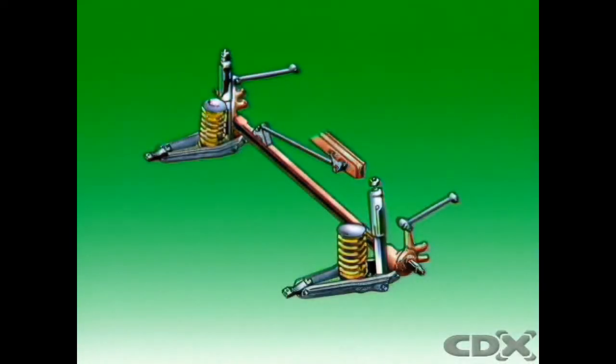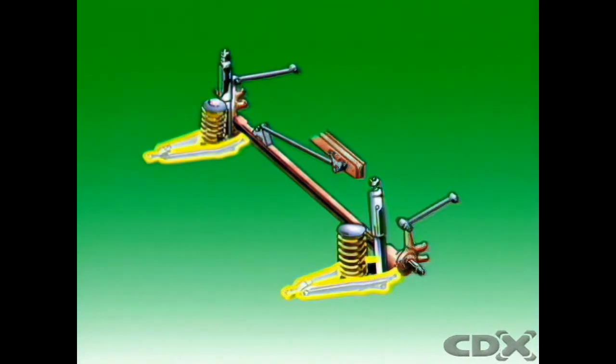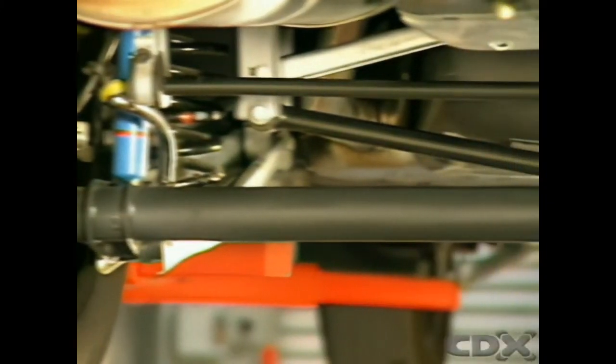On front-wheel drive vehicles, a simple beam axle can be used on the rear, with coil spring suspension and control arms for location. This is called a dead axle, since it only supports the vehicle and doesn't transmit any drive.